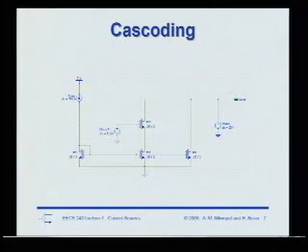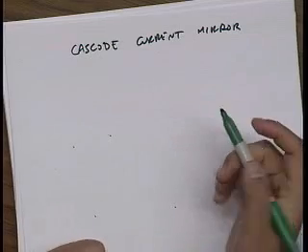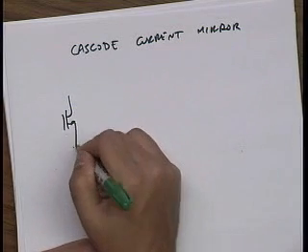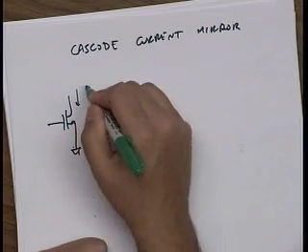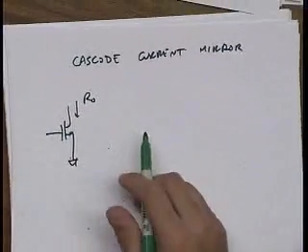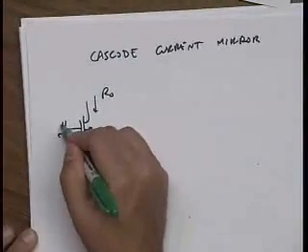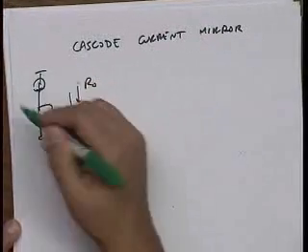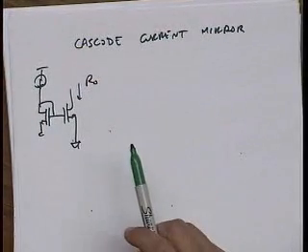All right. Well, cascode amplifiers are very nice. So are cascode current mirrors. The idea of a cascode current mirror, of course, is to use that degeneration to get even higher impedance. So first of all, before we talk about cascodes, what can I do to increase the R out of a current mirror? Obviously, cascode is one way to do it, but what are some other techniques to use?